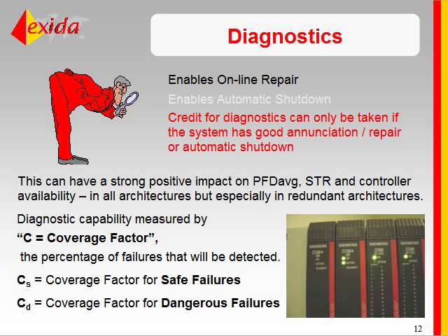And the problem was, quite seriously, like in the mid-1980s, everybody defined what diagnostics was. They could give you a nice mathematical, theoretical definition of diagnostic coverage factor. But nobody had an analysis method to measure diagnostic coverage. And of course, to really do a good job of probabilistic modeling, we'd like to know what the diagnostic coverage factor is for both safe failures and dangerous failures, at least as defined by IEC 61508.